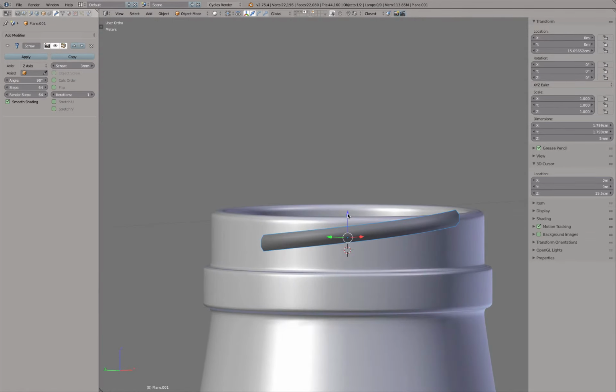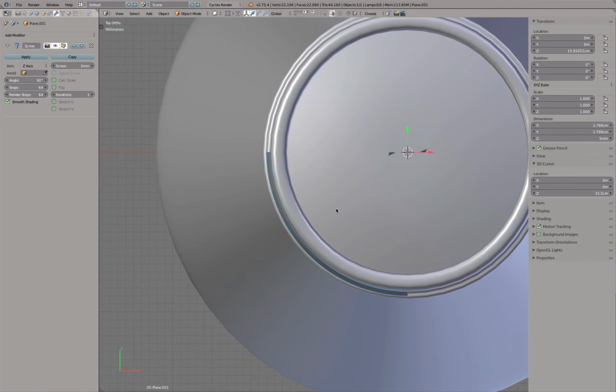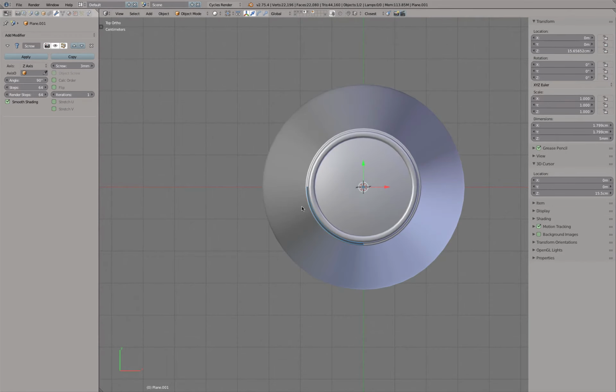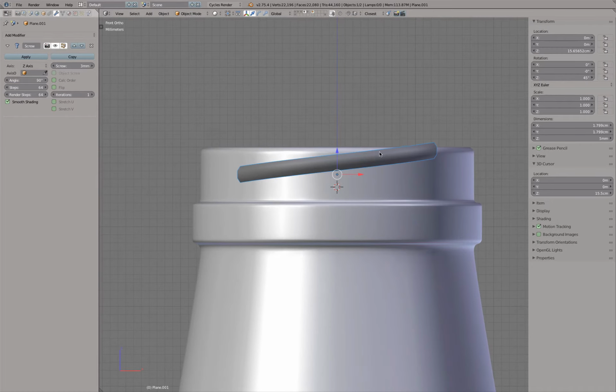And now I can, for example, visualize this a little bit better. No, unfortunately, this is not at a front view. It's kind of like a quarter view. So this object, I'm going to, in top view, rotate by minus 45 degrees. Could also simply type in 45 degrees here in rotation. And then if I press 1, I have the threading right in front of me.